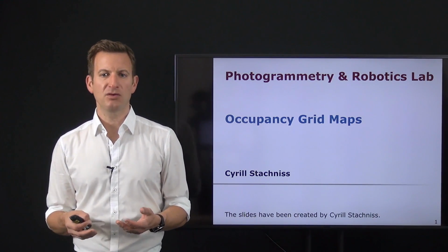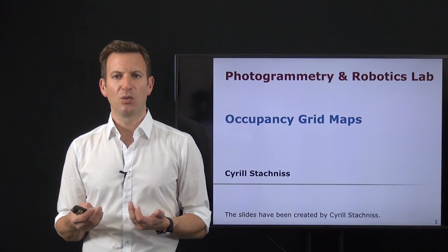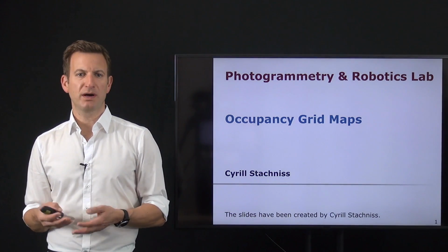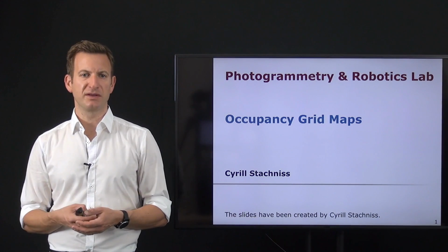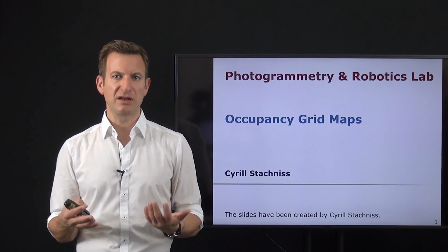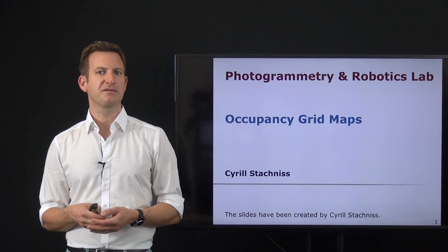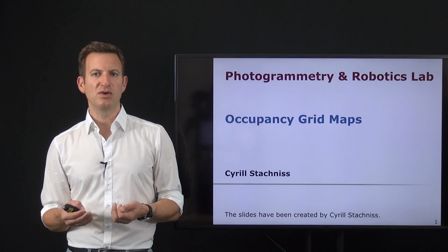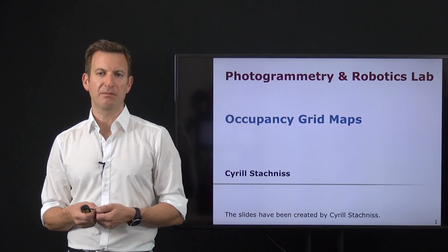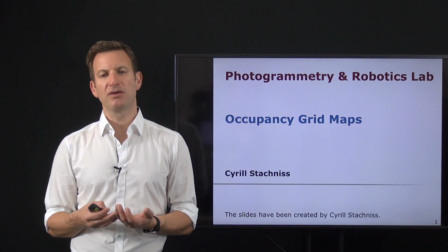And these occupancy grid maps can be seen as kind of architectural floor plans. What they do is basically store information about which parts of the environment are occupied and which parts are free. You can see this in a very similar way when you want to rent an apartment. The landlord typically sends you a floor plan, so you have an idea how the layout of the environment is. And what's written in this floor plan are typically the walls. The walls are painted with black ink, for example, and white represents free space. And occupancy grid maps can be seen as very similar to that.